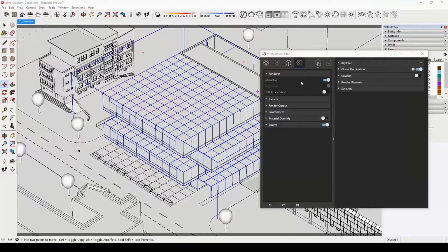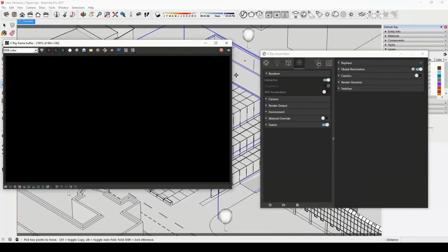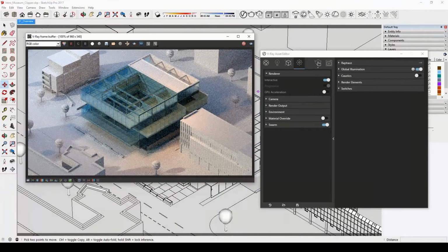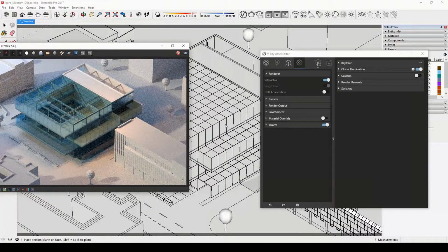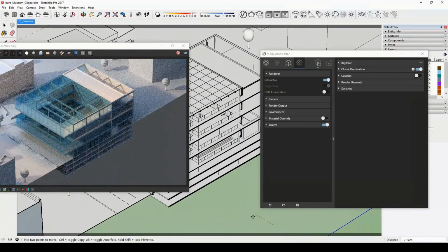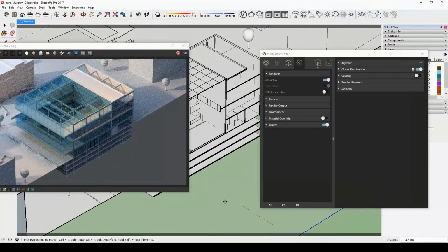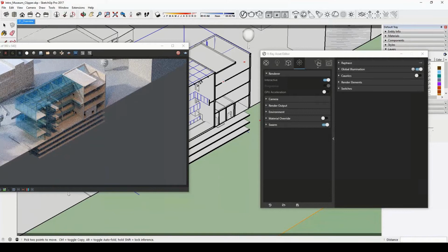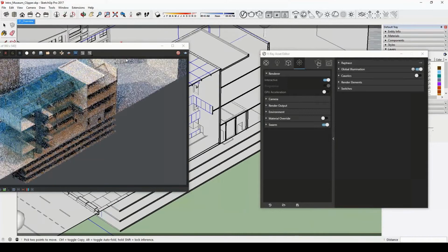All right, so finally, the V-Ray Clipper. By default, the V-Ray Clipper supports the section cut tool that's built into SketchUp. So you don't have to do anything special to get it to work. You can just apply a section cut and it will cut through the model. And any object that's a solid that's cut will use the material that's applied to the object for the cut material. So you'll notice it's kind of hard to see at this zoom level, but the glass is still glass at the edge cut, and the solid white material is still the solid white material.